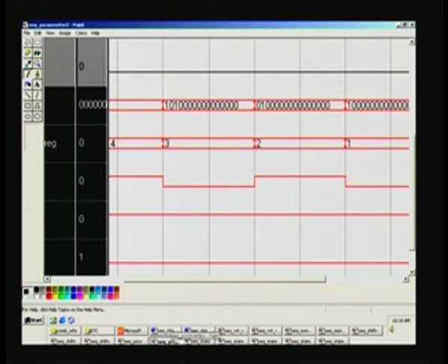You have only to, let us say, whatever signal that you are considering, let us say signal x, that is level you have to sense. If within an always block, a positive edge clock, etc., you write if x equal to 1, then you do this. So that is what you want. So that is not an edge but actual level, right. If you want level to be 0, you can take action based on that. You have only to say if x equal to 0. So, right.